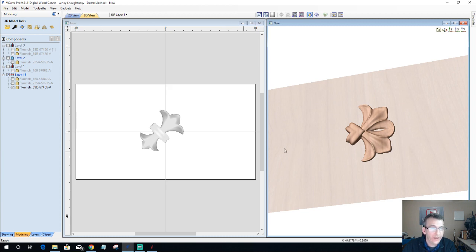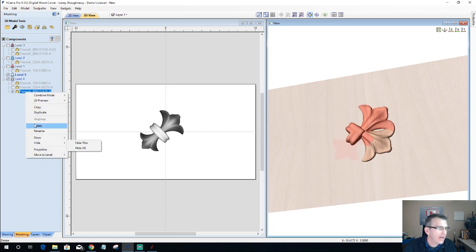now I want one on the other side. Then I could create an all new level. Insert a new level. And on that new level, I could change that mirror mode. Let's get a copy of this. Let's right click and copy this and come into this level.